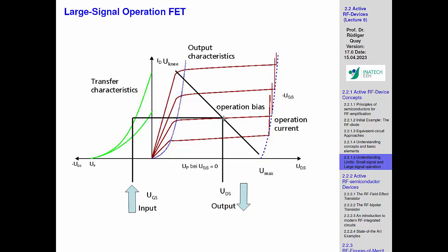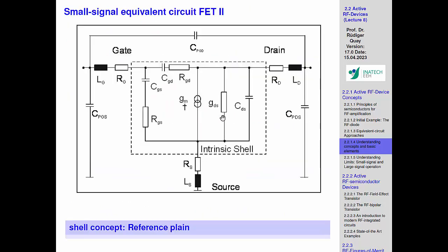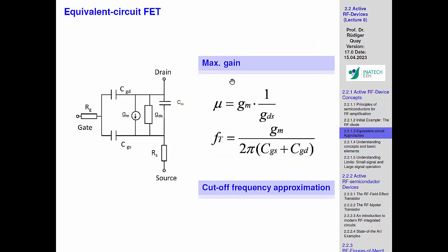So you can suddenly see that you're modulating power. And here you also for the first time see this GDS argument. In this region, the current is essentially changing with the voltage, so that's very steep. When you increase the current, you also increase the voltage. In this region, the voltage is steady, and the more steady and relatively flat this is, the better. So this is just a justification of this formula here: it's not just about this forward current change, but also about this being low.